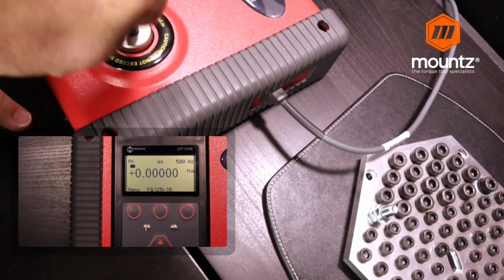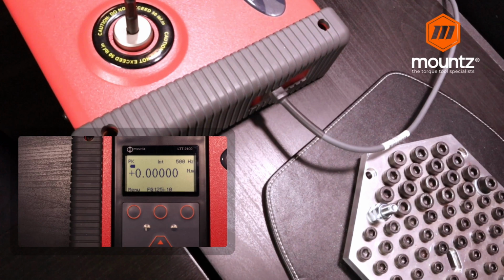And now all of the readings that the tool has taken within that particular test are all time and date stamped. And again, it gives us the ability to look at how the tool is performing during the validation or verification process. If you don't necessarily want to use a rotary type of sensor, you could still use the internal sensor on the torque analyzer to do that. And the tool test function is an easy way for you to grab that information, again, with the time, the date, and the data for that particular tool on that particular test.